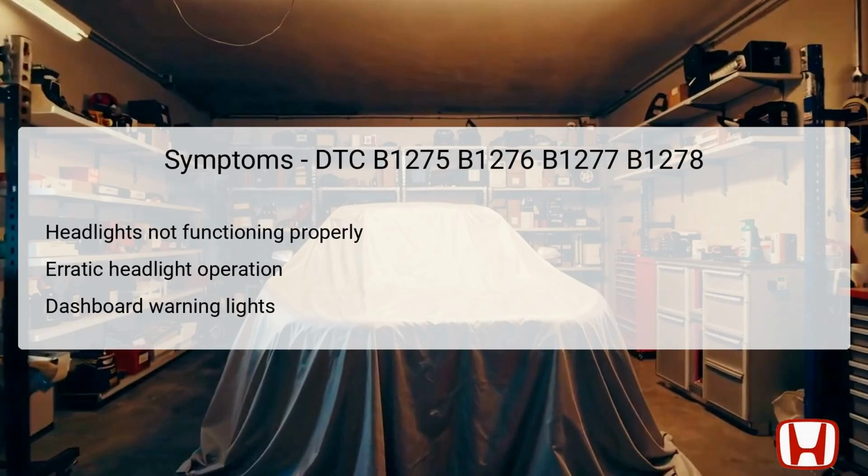Symptoms associated with DTC's B1275 through B1278 typically involve issues with the headlight operation. Drivers may find that the headlights do not operate as expected, experiencing either complete failure or erratic behavior, such as flickering or inconsistent brightness. Another common symptom is the illumination of dashboard warning lights that are indicative of a problem in the lighting system. This can cause significant concern while driving, particularly at night or in poor visibility conditions.